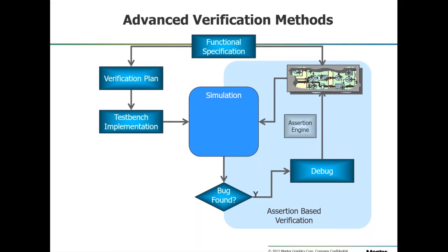And the last benefit with assertions is that you bind them to different modules. And the reason that becomes powerful is that in the next generation, I'm going to pick this block up and reuse it, but I'm going to have 3 of them. I'm going to throw away this parallel interface and make that a serial interface. Maybe I'm going to mux those together.